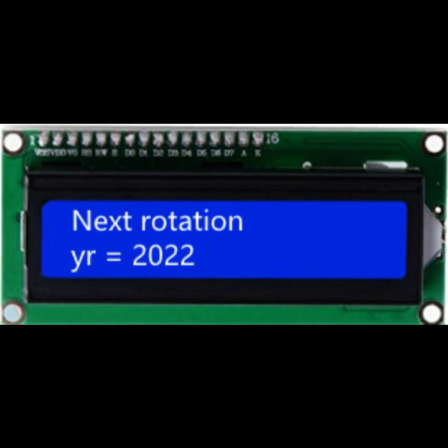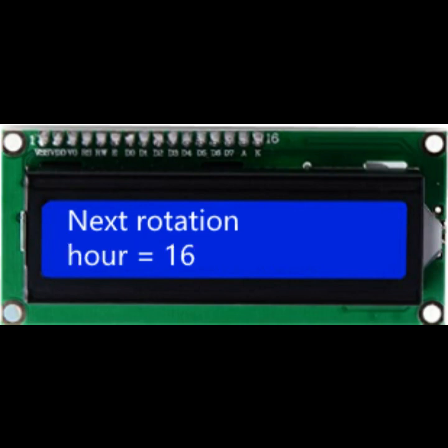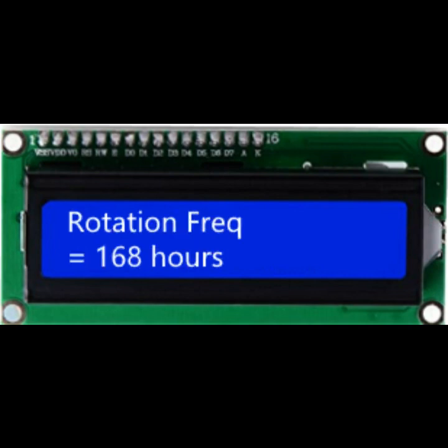Next rotation year, month, date, hour, minute. This is where you can set the date and time for the next lead lag rotation. If the rotation frequency parameter is set for 0, these menu items will not display because that inhibits lead lag rotation. This automatically gets set when the ACO does a scheduled rotation based on rotation frequency.